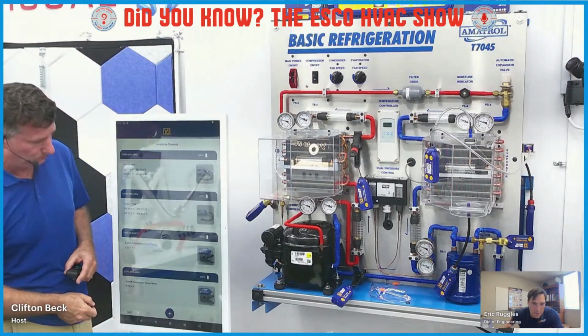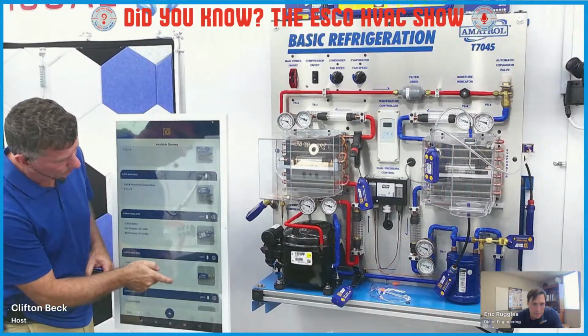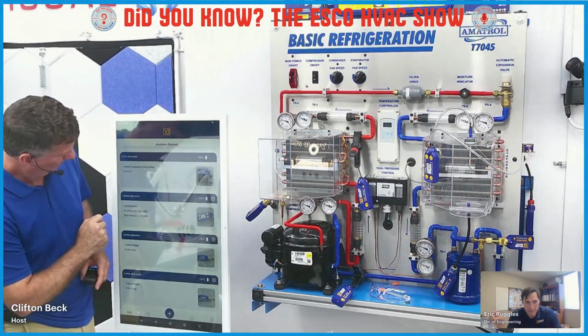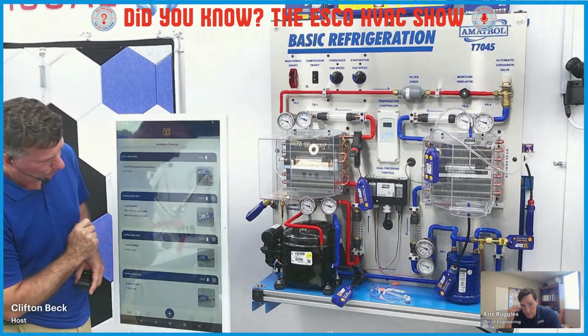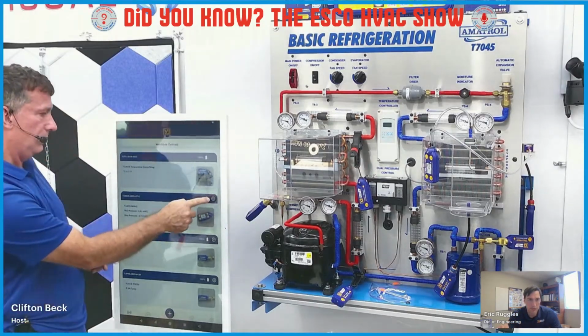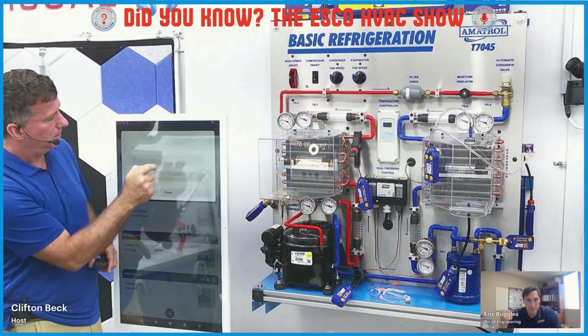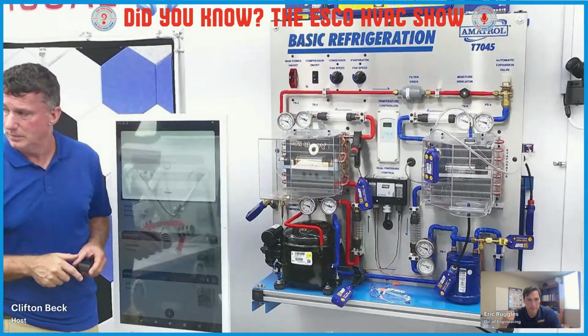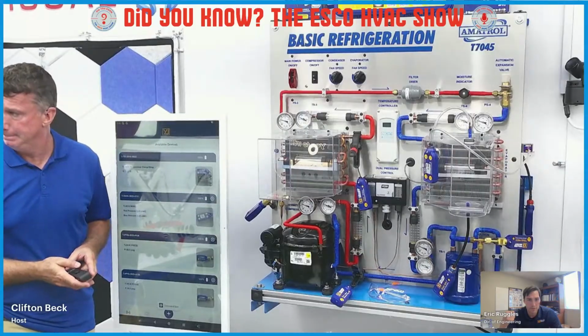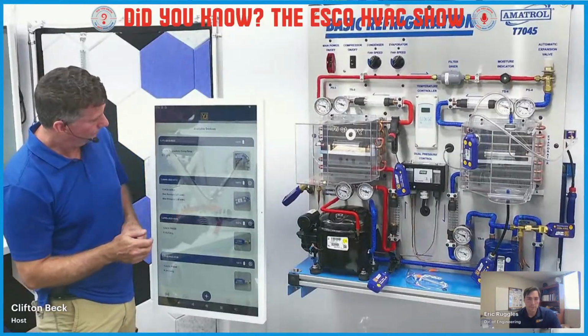Okay. And find your manometer. Scroll down to find your manometer. And there's a little gear key on the right side of that blue bar at the top of the manometer one. Step back for a minute. Little gear logo. Yep. Click on that. And then it allows zero pressures. There you go. Perfect. So you should be able to go back to that session and it should be zeroed out.